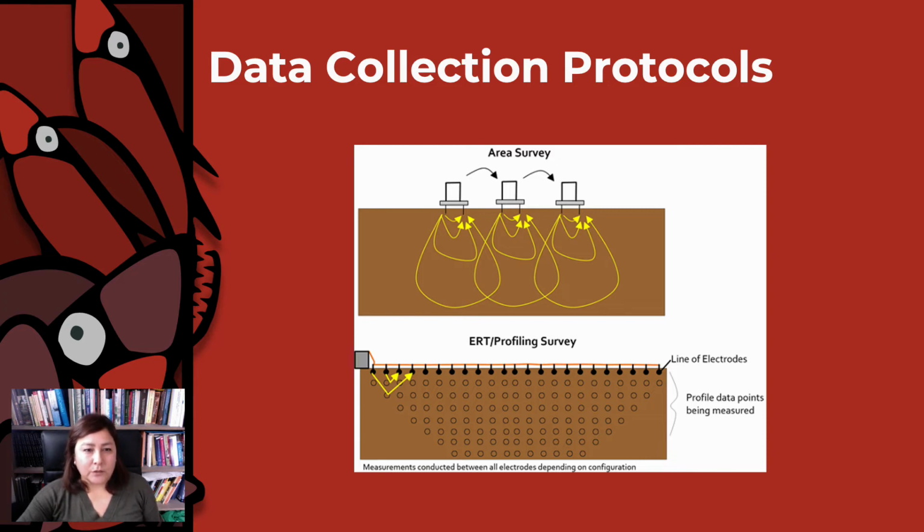Each of the electrodes is connected to a cable that connects to the resistivity meter. The meter is pre-programmed with different electrode arrays that run resistivity tests between the electrodes. It's important that the cables, electrodes, and meter are not touched or changed until it has finished its calculations. You may need to improve the initial contact resistance between the electrode and the ground by moistening the insertion point around your electrodes with water.